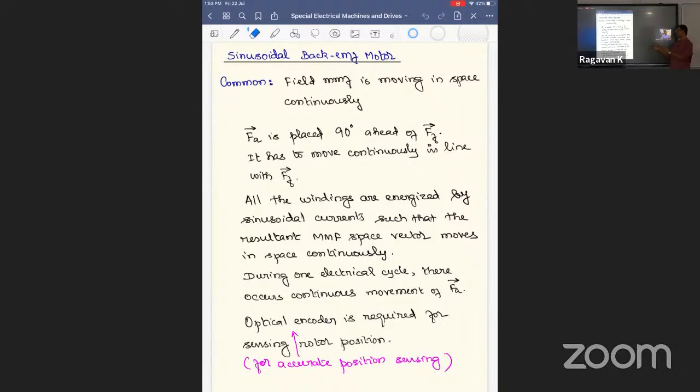So this machine cannot be recommended for a 2-wheeler, which I told earlier, but I am repeating it because the optical encoder is expensive. So it goes to the consumer only. That is why most of the machines are brushless DC motors. If at all they switch from BLDC to PMSM operation, in the sense that all the 3 windings are energized, at that time they go for sensorless control.